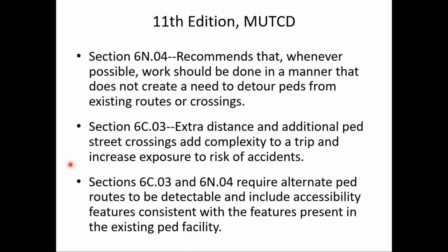Now let's look at the MUTCD. You can see here the MUTCD talks about working in a way that doesn't create a need to detour pedestrians from existing routes. They note that extra distance and additional street crossings add complexity to a trip and increase exposure to the risk of accidents. Sections 6C.03 and 6N.04, which I just cited, require alternate pedestrian access routes to be detectable and include accessibility features consistent with the features present in the existing pedestrian facility.